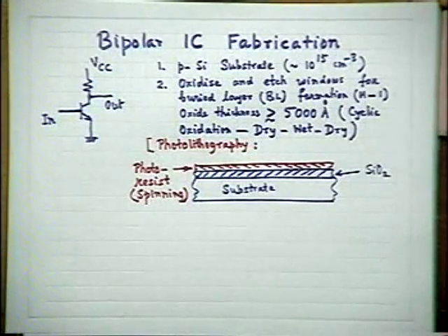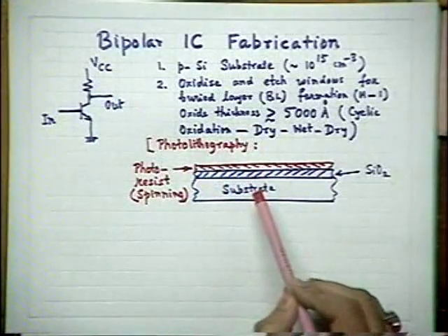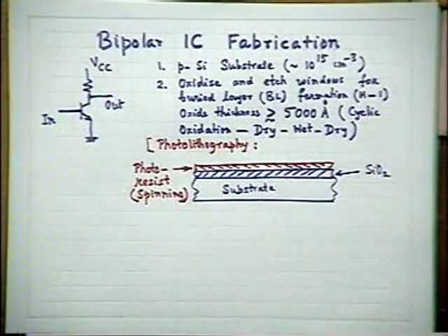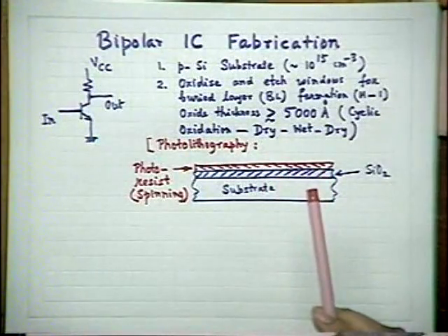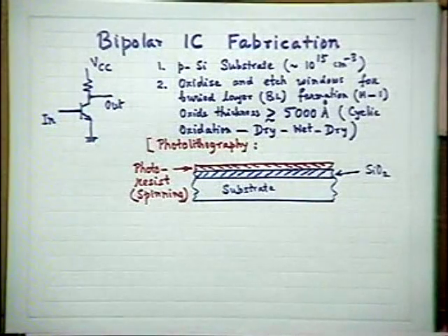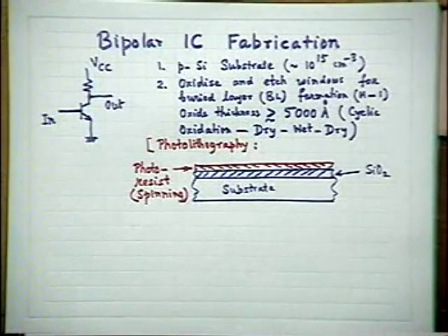You know that photoresist is a very thick liquid, something like an emulsion type of material. If you put a few drops of that liquid on the oxidized silicon substrate and then spin it at very high speed, the photoresist film spreads uniformly, and you get a very thin layer of this material, thickness being of the order of 1 micron. Maybe less than a micron or a little bit more than a micron. Usually that is the thing.